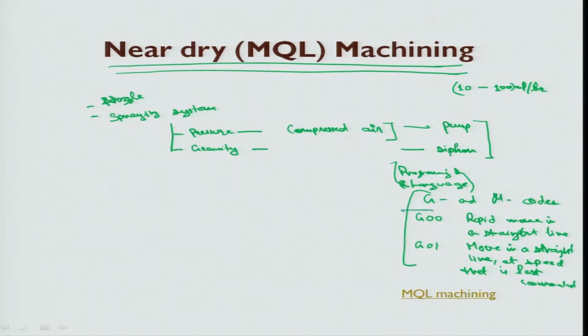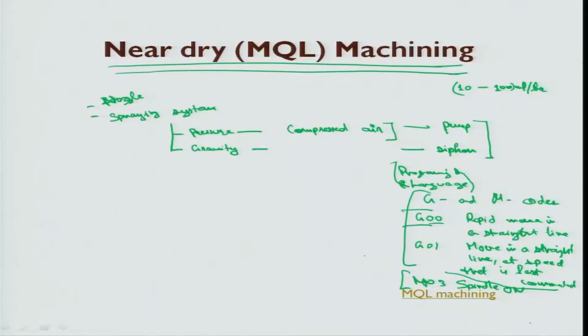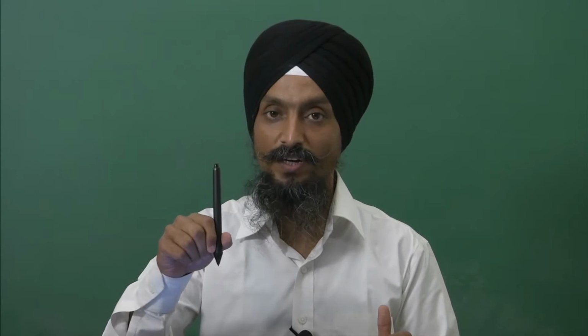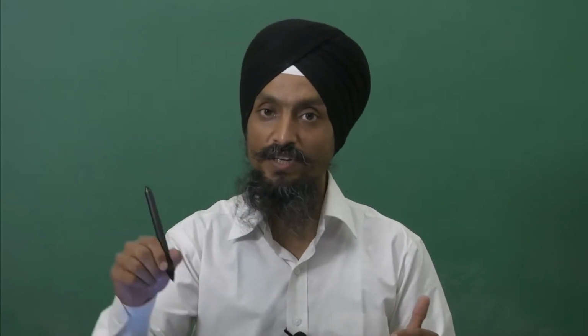Why I am telling this is, the longer the machine would run, the more energy would be used, because when the spindle is running we use this code M03 to switch on the spindle. This is spindle on. I will come up with the full code of this simple machining in the forthcoming class. When the spindle is on, some energy is being consumed, and the level of energy consumed rises. So at this state the movement of the tool has to be minimum. For that this rapid move G00 code is used: the tool moves up and rapidly goes to the other position from where machining is to be started. In the case of drilling also this rapid movement was there.